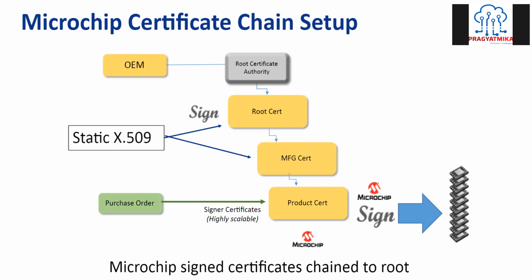One is your private key, which is from the manufacturer, and then we have the public key from the cloud side. Both of these need to be signed, and then it has to go into your chipset, that ATECC608A. Further signing by the vendor and the manufacturer of these semiconductors together leads to the creation of this root of trust, and it has this X.509 certification. That's a certificate signing thing that is required.